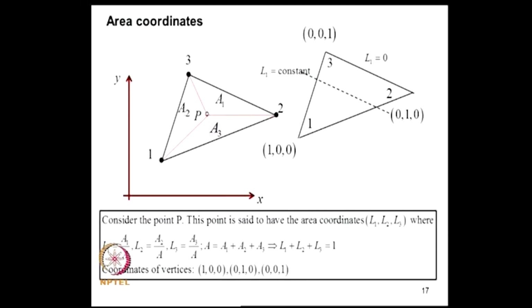Before we start discussion on thick plates and other issues, we will revert back to a basic notion that in dealing with triangular geometries, we can introduce, instead of the Cartesian coordinate system, what is known as the area coordinate system. To explain that, you consider this triangle 1 2 3, and for any point within the domain, I construct these 3 triangles, and the triangle opposing node 1 is called A1.